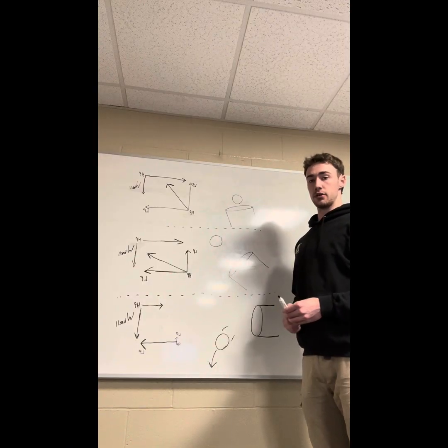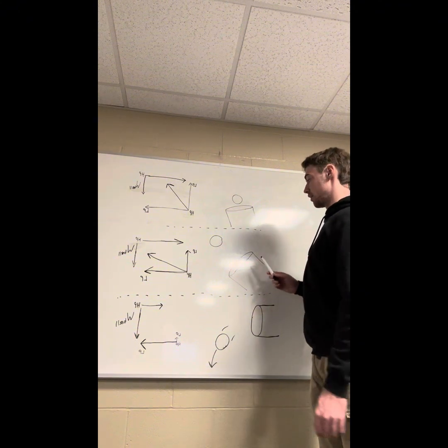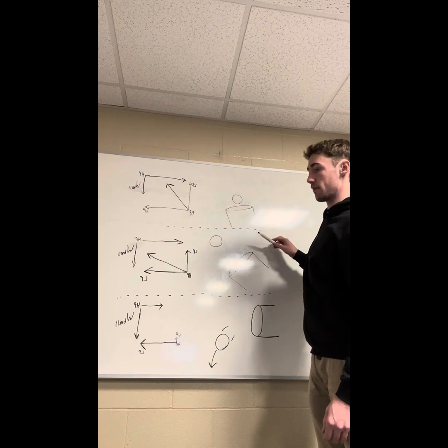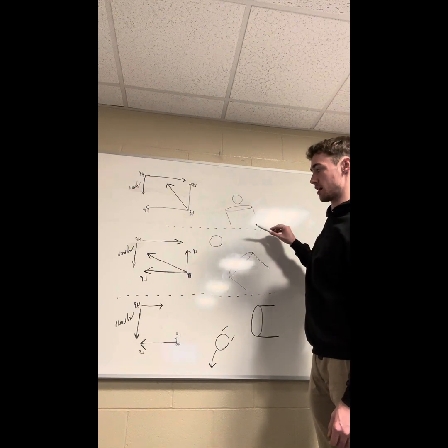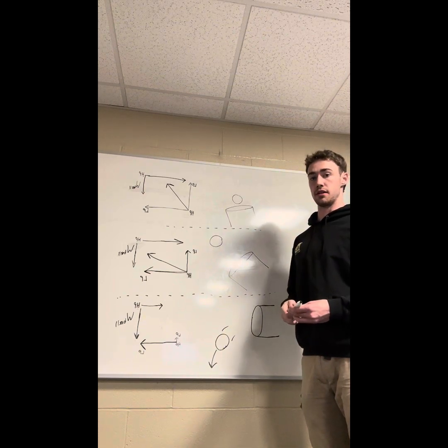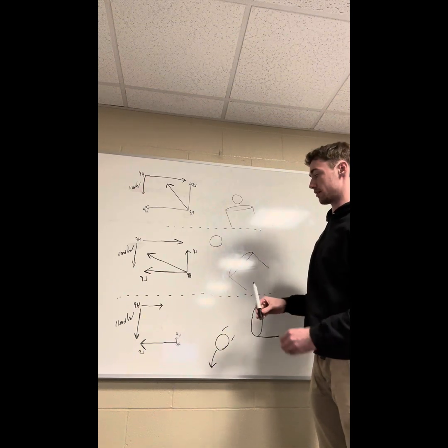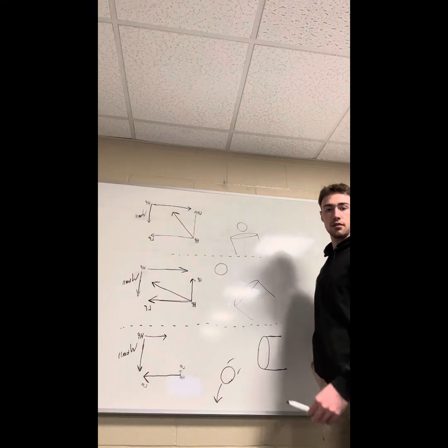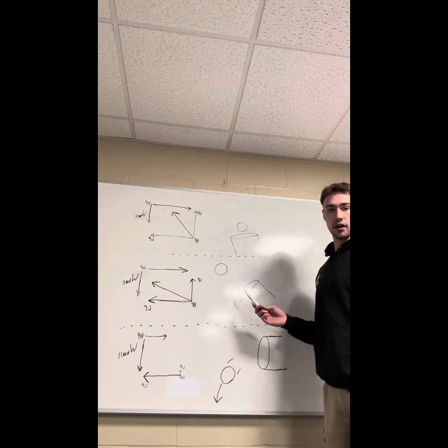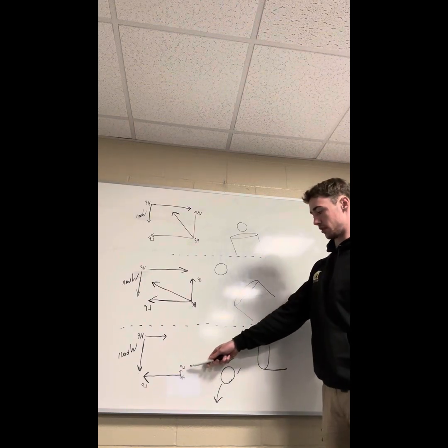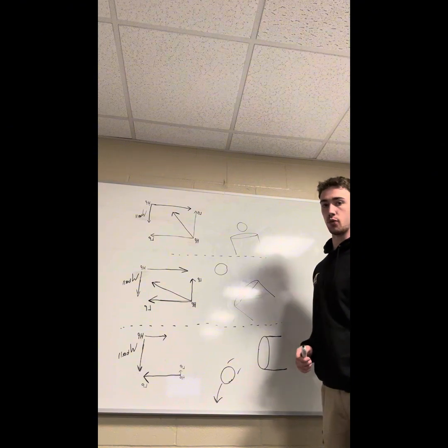The reason the ball increases its distance from the hairdryer as the angle of the hairdryer is increased is because this transfers more of the pressure difference to act horizontally on the ball rather than vertically. But at the same time, this means that the pressure difference that acts vertically and supports the ball's weight is decreased. This means the ball's distance from the hairdryer will increase as the tilting of the hairdryer increases until there's not enough of a pressure difference between the top and bottom of the ball to support its own weight.